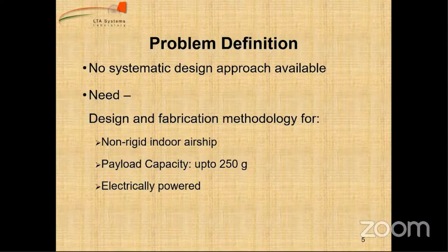For lift generation, we can use gases inside the envelope. Yes, but the propulsion system on an airship, we don't use it mainly for lift generation. We use it for the forward motion, or if we want upward motion, we can put in a thrust vectoring and get lift in an upward direction. But generally, with the help of the propulsion system, we would like to get only forward motion. We get lift by buoyancy and with the help of a lifting gas.